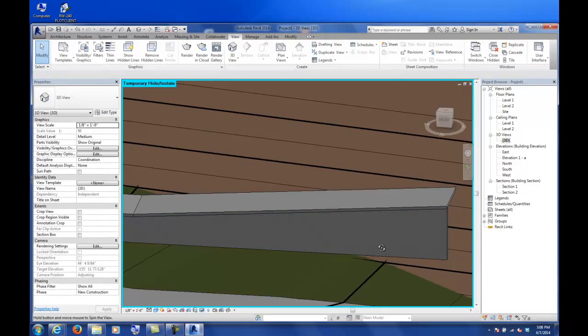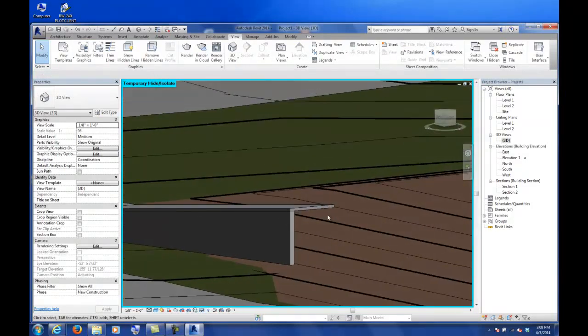And that would get that wall to be exactly how you want it to align with the bottom of the ramp. This way then you have more control over the materials and how that's going to look. Could you accomplish the same sort of thing, not a brick, but with a pad under the ramp? Not necessarily, because the pad is always going to be level.